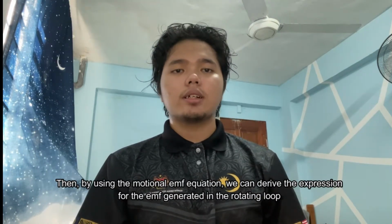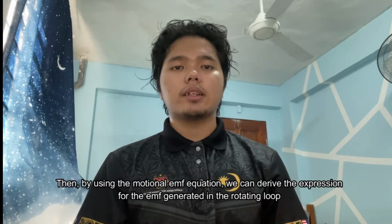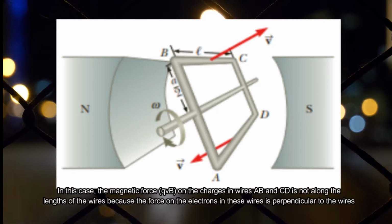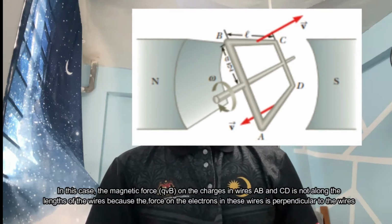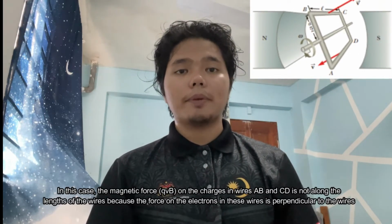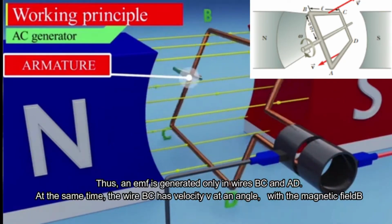Then, by using the EMF equation, we can derive the electromotive force generated in the rotating loop. Based on the figure, we can see that the wire loop is rotating clockwise with the uniform magnetic field directed to the right. In this case, the magnetic force on the charge in wire AB and CD is not along the length of the wire because the force on the electron is perpendicular to the wire. Thus, an EMF is only generated in BC and AD.